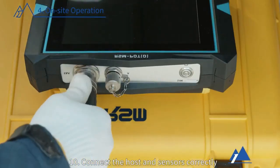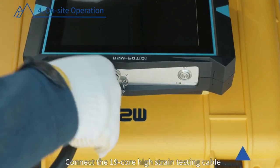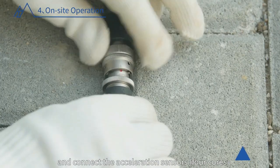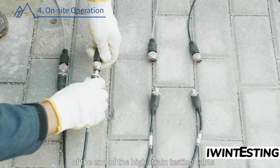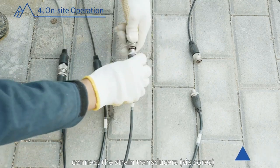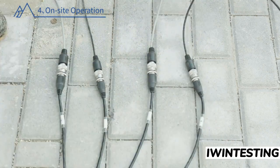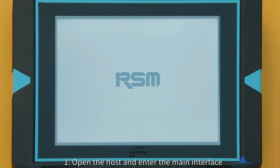10. Connect the host and sensors correctly. Connect the 19-core high-strain testing cable to the interface of the host, and connect the acceleration sensors, 4 cores, to number 1 and number 2 interfaces at the end of the high-strain testing cable. Connect the strain transducers, 6 cores, to number 3 and number 4 interfaces on the other end of the cable, respectively.